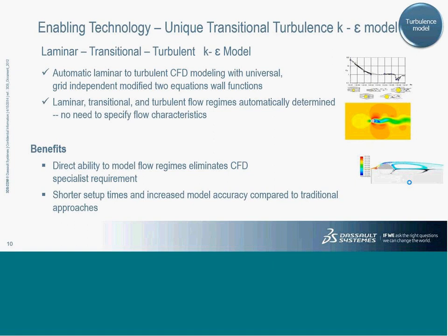For some, we can force the software to solve it with laminar or turbulent conditions. If we leave it for the software to decide, then it can understand based on the turbulence that is created, the Reynolds number, based on the velocities, to decide whether a turbulence is occurring and it has to be used. We will use the K epsilon model, and it's definitely not taxing anything on the user. The user will not worry about this particular topic.